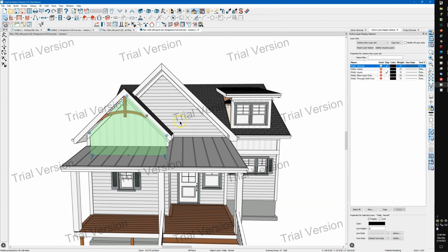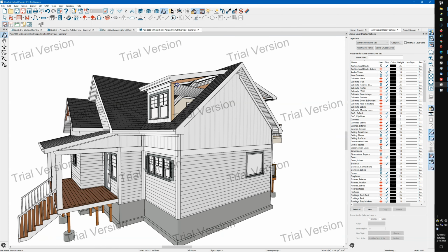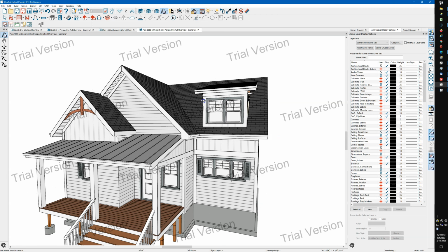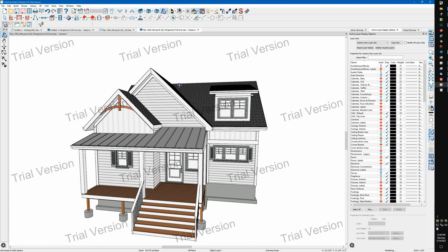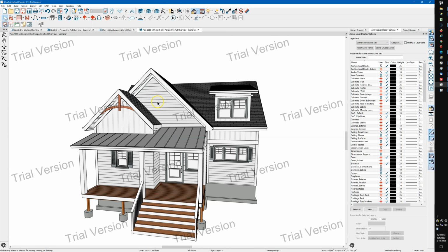And then what you would do is you would just redraw or change the wall type for these attic walls to be that board and batten type. Now don't worry about this. This was something I did, just testing something. So that's what you would do here. You know, I'd make a new wall type, board and batten, and then open this wall, and change them to board and batten.